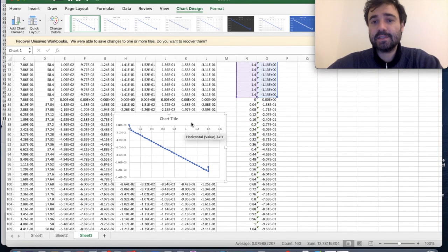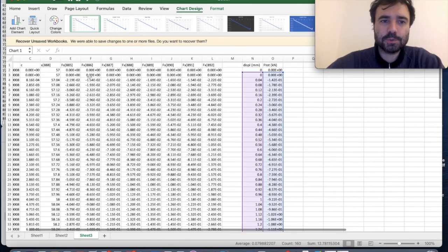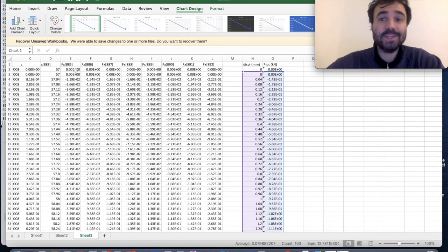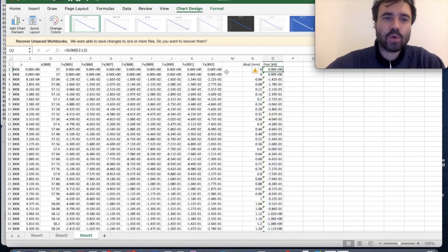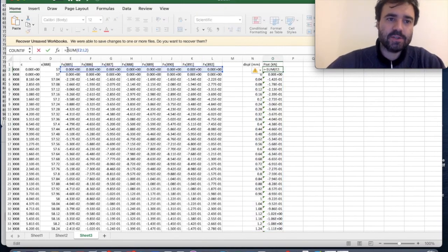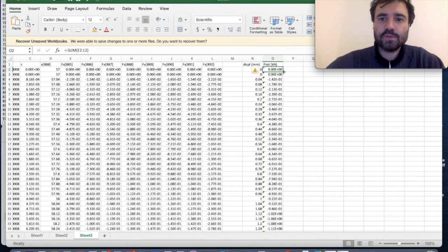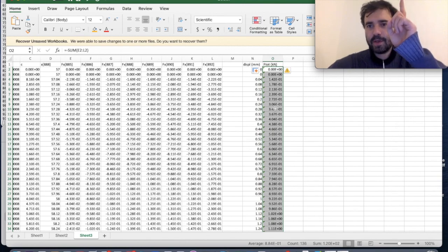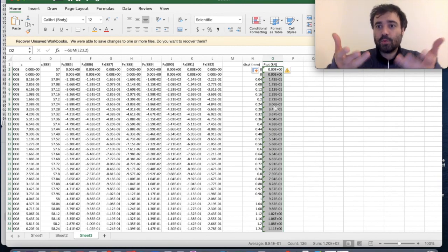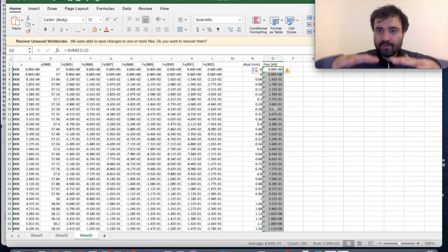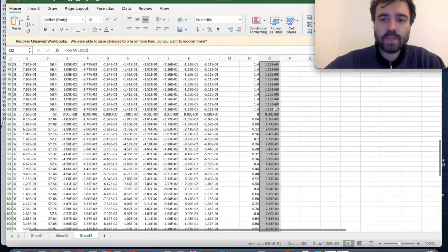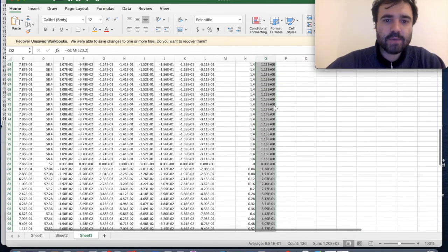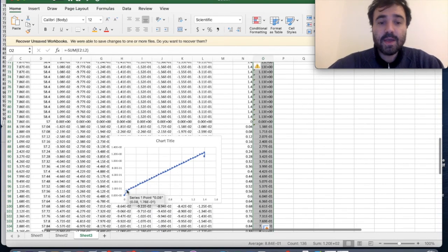The force is negative because what we are plotting here actually, I forgot to mention in the previous video, is the reaction provided by the particle. So if you want to see the force that we are applying, actually you should put a minus sign. The same was true for the previous video where we had the positive force in Y, which means up, and that was the reaction of the particles that were trying to contrast the vertical displacement we were imposing. So now that we put the minus sign, we get all these being positive.